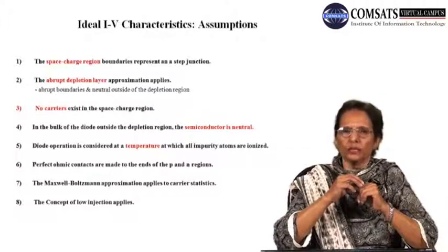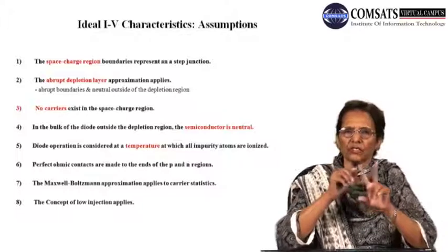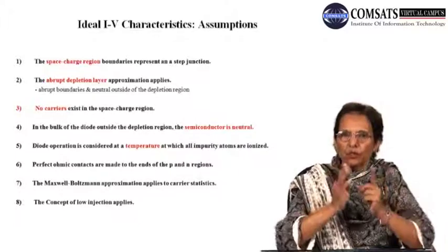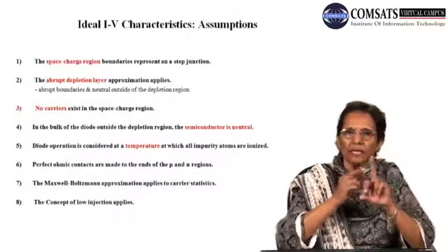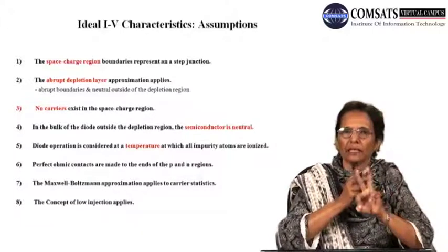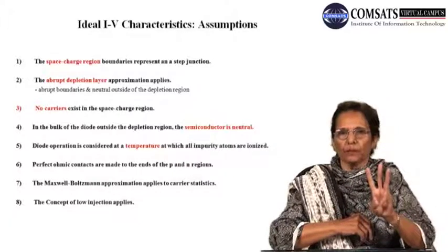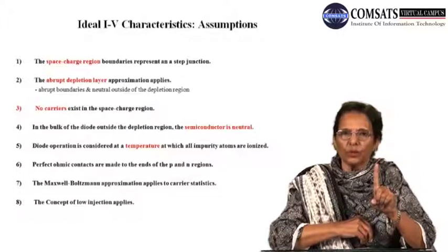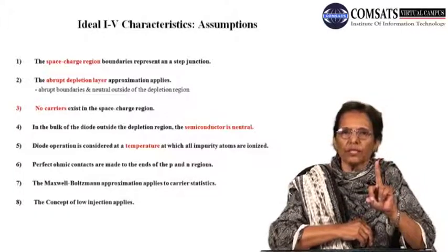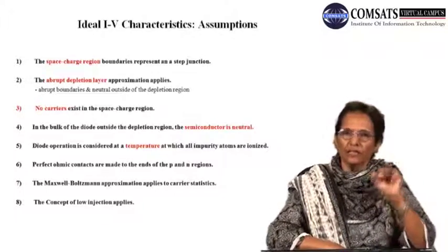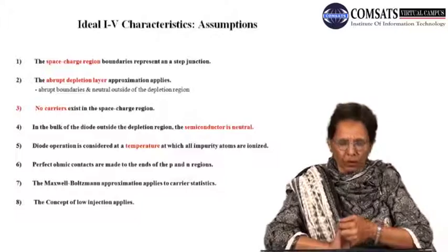What happens to the diode characteristics, the depletion region characteristics? The depletion region across the interface reduces and becomes small in width. The electric field also reduces, and the barrier potential also reduces. So there is a reduction in all the junction parameters: the depletion region width decreases, the electrostatic potential decreases because of the applied potential across the junction, and finally the electric field also weakens.